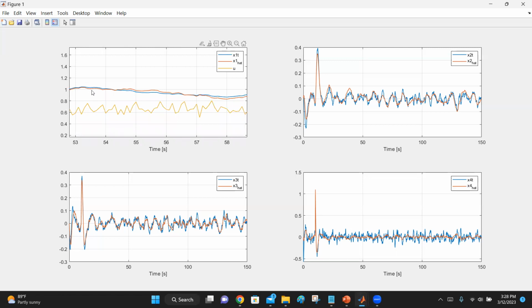But you don't see the level being maintained. It goes up and down around 1. Okay, so this is the reality. Most of the curves that you have seen earlier are hypothetical or ideal conditions, very flat curves maintaining zero steady state error like that, right? Hardly found in reality with noise and all. And this is the control signal. You can see it goes up and down, right? It's a kind of restless signal. When you deal with a lot of noise and a lot of estimations, this is pretty much the commonplace scenario.